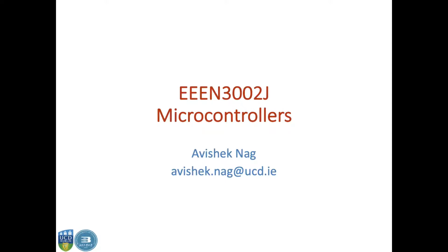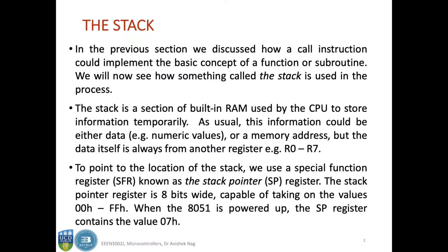So today we will start with the stack. It's a special function register, and we will study what are the functions of this stack in today's lecture. In the previous section, if you recall, we discussed how a call instruction could implement the basic concept of a function or a subroutine. We will now see how this stack is used in the process.